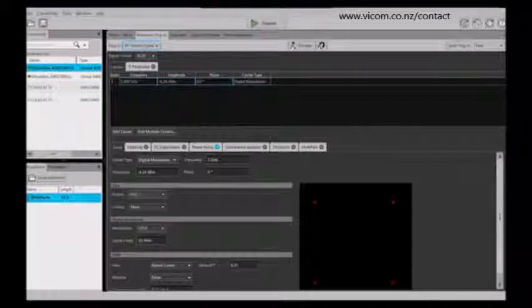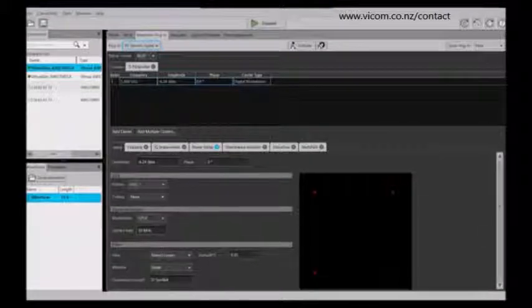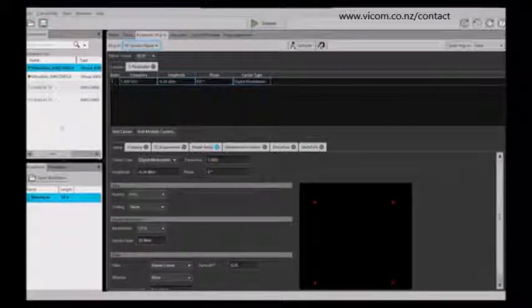As you can see here, you have the total graphical interface of the software itself. If I take a tour around the interface here, as I mentioned, this is your AWG connections, and then you have your waveforms listed here. If you have sequences, you can go in and list your sequences also from this table. In the main display is going to be the interface where you set up or create your waveform characteristics.